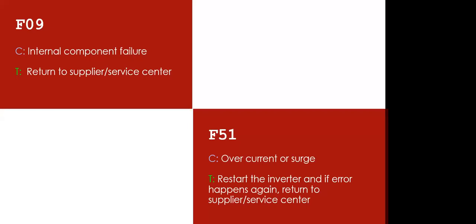After that, if the inverter is working on battery mode, it means that the inverter is still okay, until you introduce another parameter, maybe grid, and it starts showing a fault. Then you know that the fault is coming from that particular aspect you introduced.